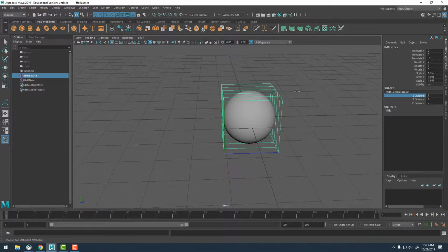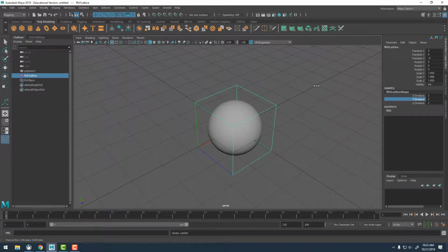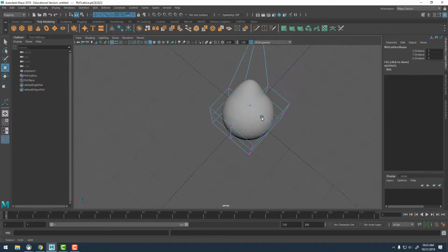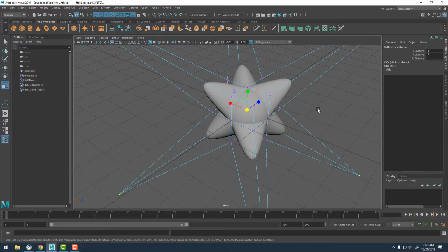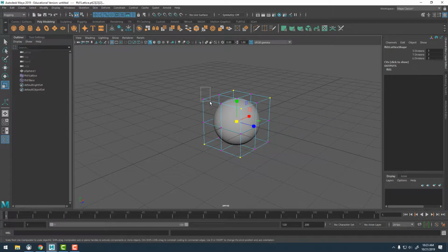So the S direction is going to add it going this way, around. Again, the T direction is going to go around horizontally, and then the U is going to go vertically, but from the front instead of the side. And so let's set all of these to 3. And again, this just dictates how this is going to deform our geometry. Oh, missed a point there.